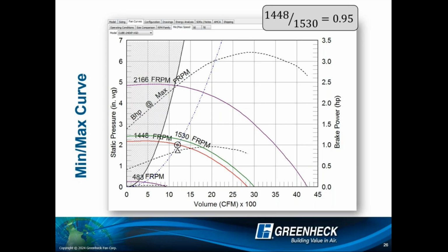motor nominal power. So if it's a 5 horsepower motor, I got to do quick math. Yeah, 4.5. So let's say your motor horsepower is 5 horsepower. You wouldn't want your brake horsepower to be more than 4.5. That's typically what I see.